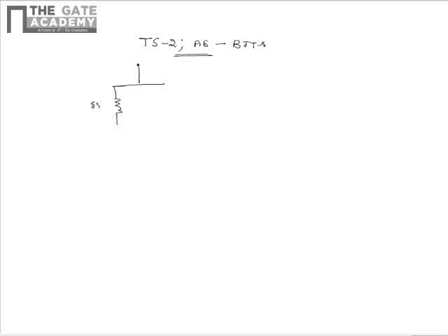It contains a 58k ohm resistor and a 42k ohm resistor whose series connection point is connected to a BJT as shown in the figure. The emitter of BJT is connected to a 10 kilo ohm resistor and the collector is connected to the input supply directly as shown.